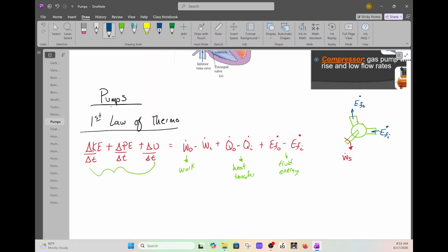All right, so these energies that I've drawn are basically on this side of the equation. Now, if this pump was moving in space and completely changing temperature, then you would have stuff over here on the left. But we're assuming it's steady state and not moving. So what we can do is cancel some stuff. Not moving in space, there's no temperature change. There is only mechanical shaft.